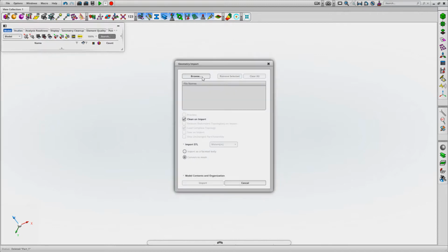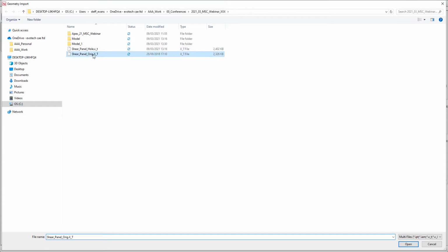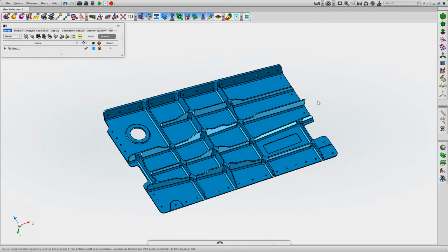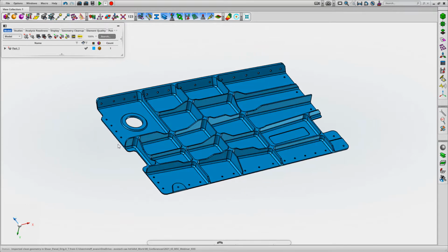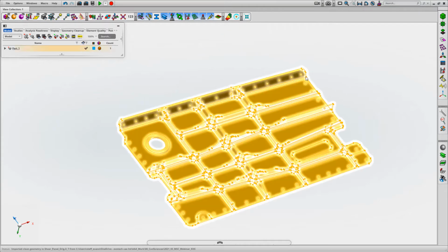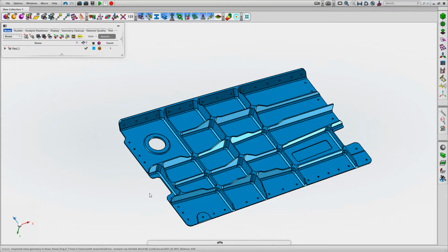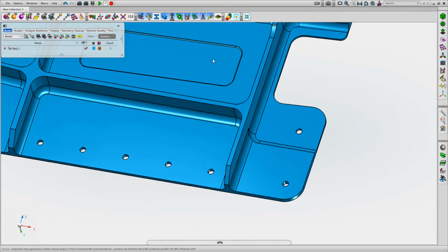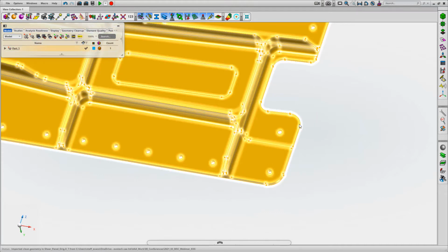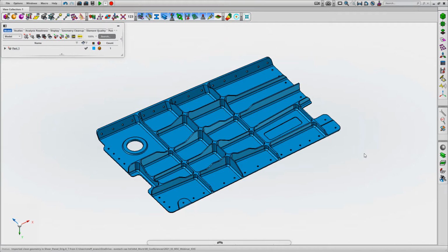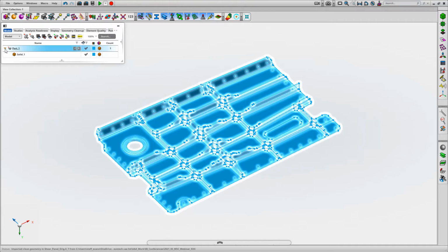Okay, so I'm just going to run through a couple of approaches for mid-surfacing and shell meshing. We're going to import some geometry that we've got access to. This is, as you'll see, a machining typical of an aerospace type component: a shear web with a series of horizontal and vertical stiffeners, a flange across the top, a series of fastener holes around the edges, machining detail, a lot of fillets, some local pockets, and some boundary holes as well. We're going to try and capture all these entities within a mid-surfaced and shell meshed model.